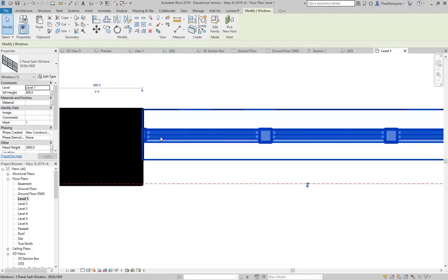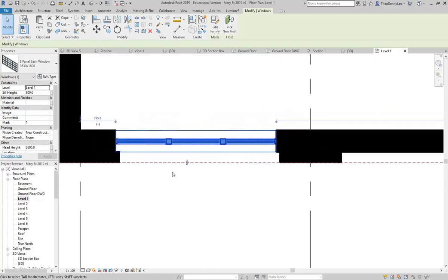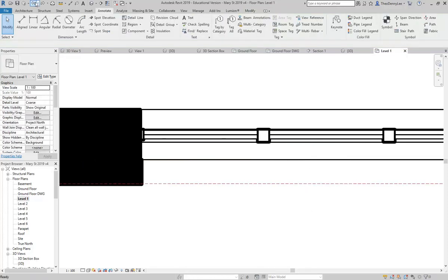And you also then need to check that it's aligned with the opening. So I'm just moving it to one side so that you can see how it might look if it's not centred. Yep, so if it's centred, that's fine, you can leave it. But if it's not centred, if it's on to one side, so if it's centred, you'll know because it'll line up with the piers exactly. And that's how mine was. I'll just go back. So mine was like that, but I've just moved it so that you can see, again, if it's not exactly right,